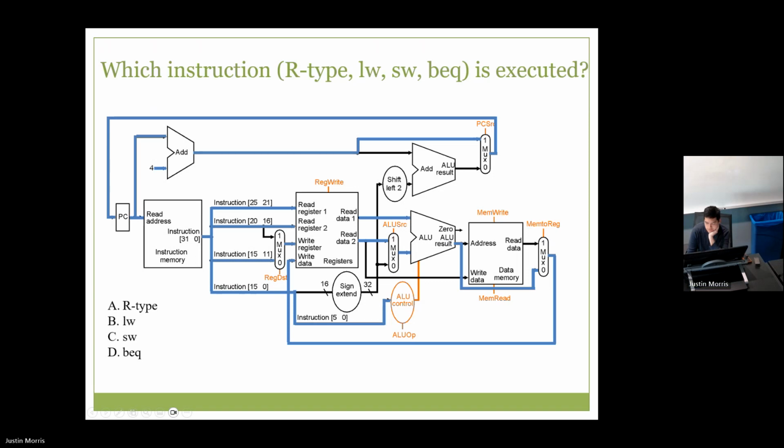And the result goes to memory, right? We take the results and we're writing that back. So this again tells me R type, okay? Because if it was load word, store word, store word would stop here. Load word would get the data from the memory and write that back. And the other thing that tells us that it's not the other I type of branching is we're not using the shifted left sign extended. We're taking PC plus 4 and we're incrementing by that.